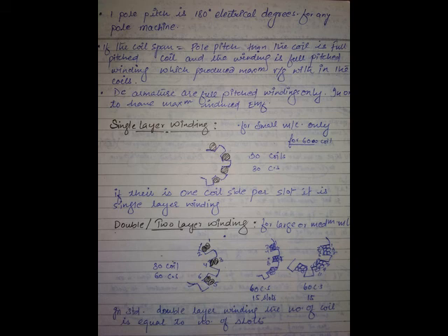But you will observe one thing. With the same number of conductors, if you are asked like this in the question, for the same given number of conductors, multiplicity increases current rating but reduces voltage rating, because as you increase the number of parallel paths, conductors per parallel path are reducing. Observe, if there are only 2 paths, 4 volts. If there are 4 parallel paths, only 2 conductors per parallel path, so you got only 2 volts.